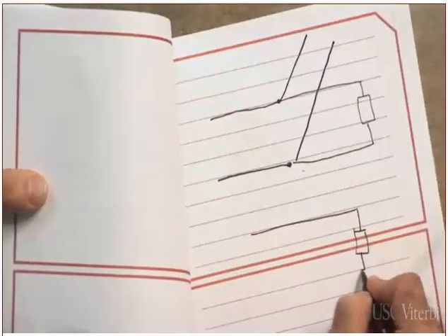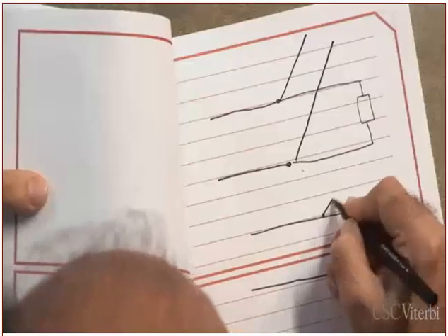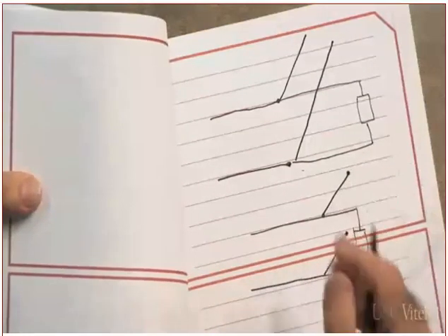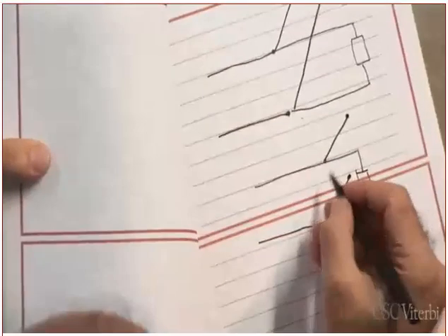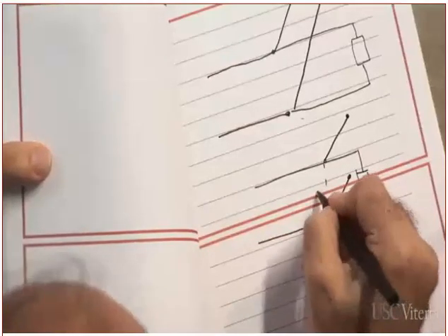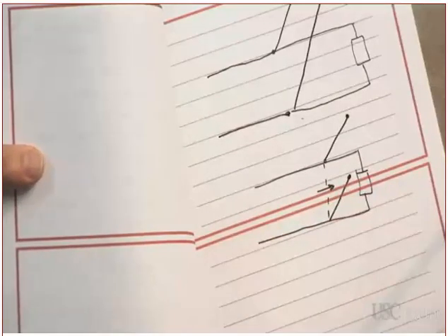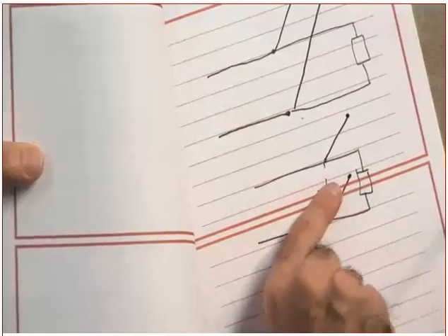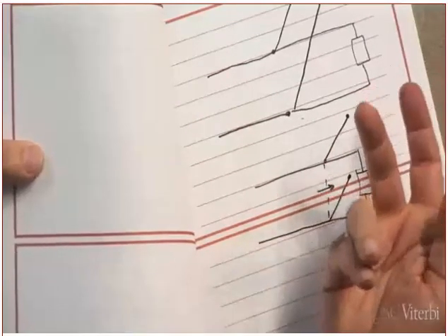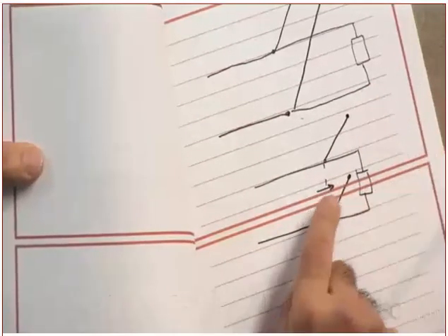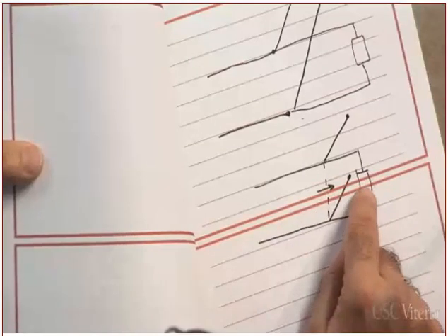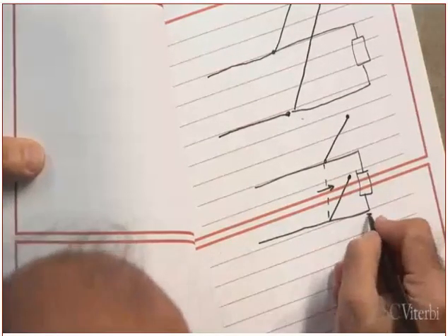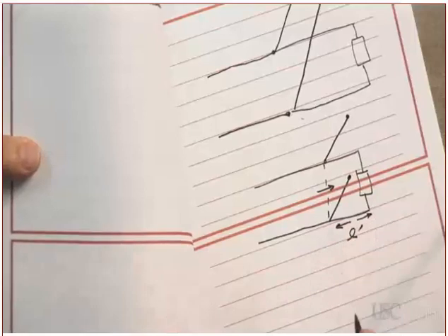This is a transmission line, and this one here is a stub. Open circuit, let's assume, just an example. Can you find me the impedance looking in here? You take the input impedance of the stub, yes or no, in parallel with the impedance looking between those two at a given L prime.